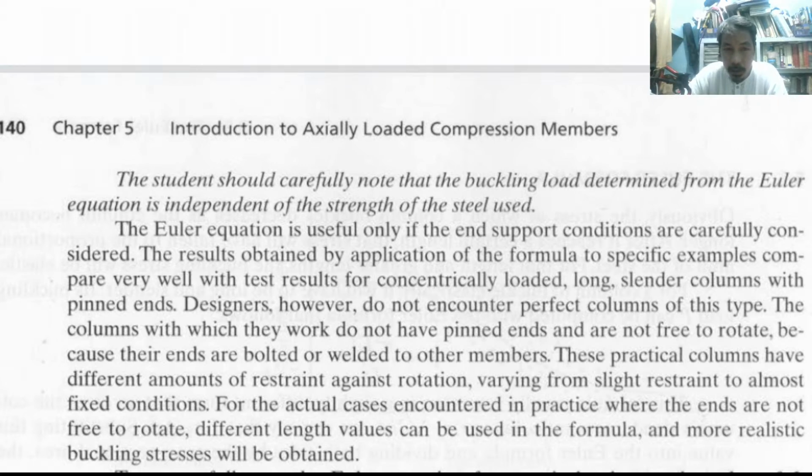Designers, however, do not encounter perfect columns of this type. The columns with which they work do not have pin ends and are not free to rotate because their ends are bolted or welded to other members. These practical columns have different amounts of restraint against rotation, varying from a slight restraint to almost a fixed condition. For actual cases where the ends are not free to rotate, different length values can be used in the formula and more realistic buckling stresses will be obtained.